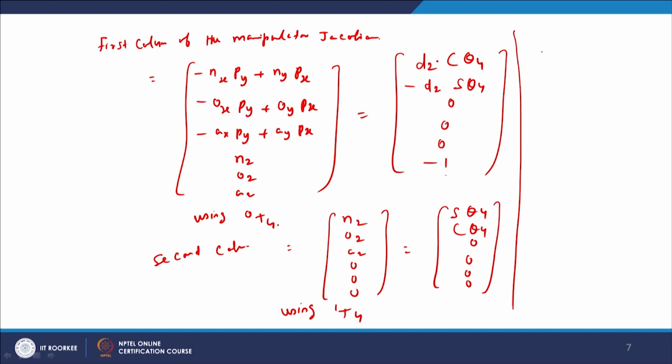If we denote the linear velocity dxt, dyt, dzt as v, and del xt, del yt, del zt as w, the angular velocity with respect to the end effector frame, it is equal to the Jacobian multiplied by q1 dot, q2 dot etc., qn dot in the general case.